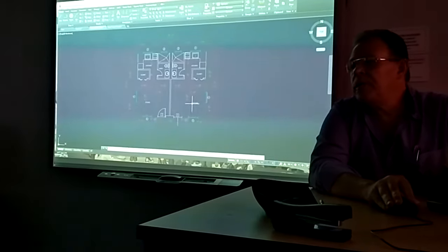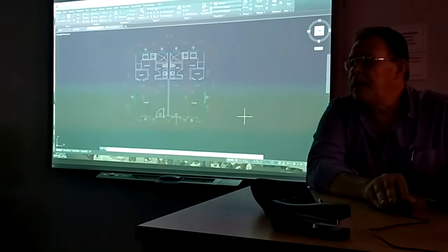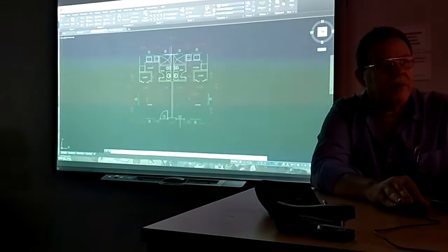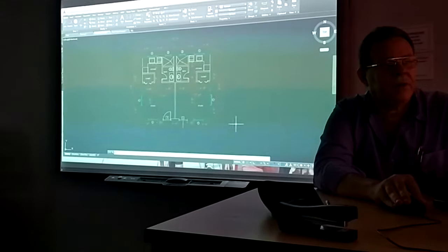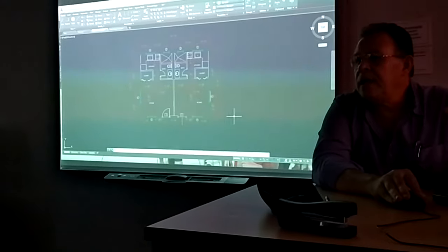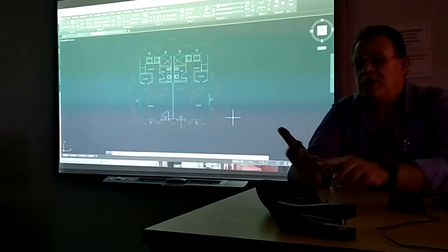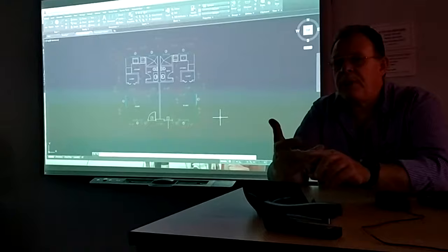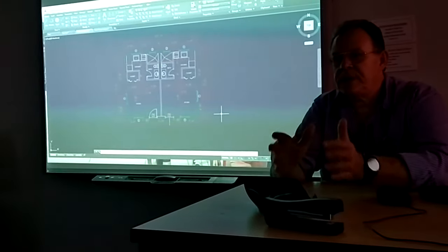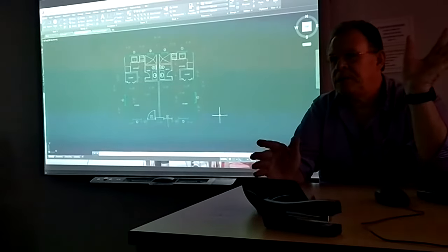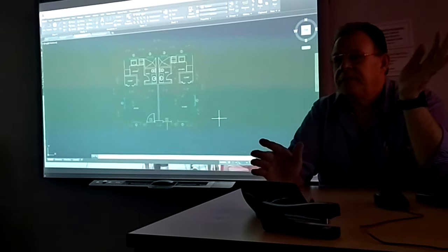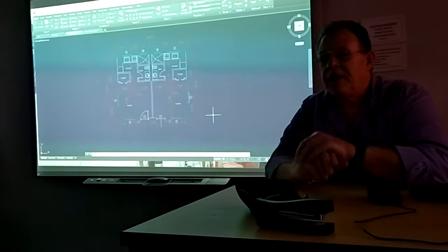The reason why we do X reference is because on the base plan, I modify any of the plan. Let's say I take out the window, I put it on the other side, I change the door and all that. And then after I change all that base plan, every plan, the electrical, the furniture, would change to the updated base plan. When I close and save my base plan, the rest of the drawings, they're changed. You don't have to change it. You don't have to do any drafting. You have to only modify the lights. Anything that